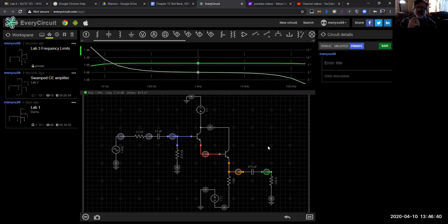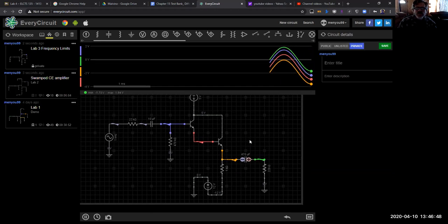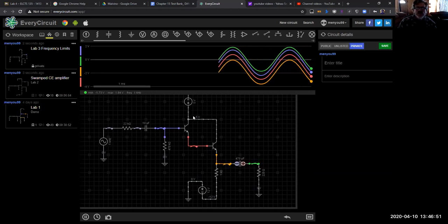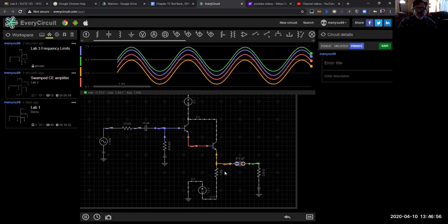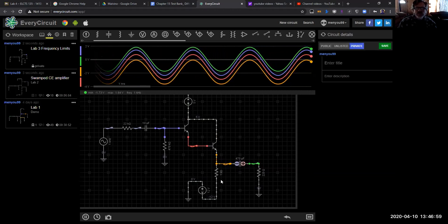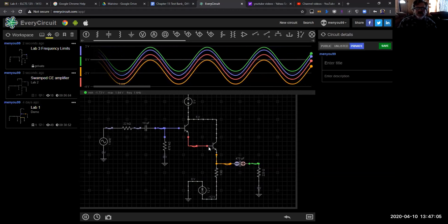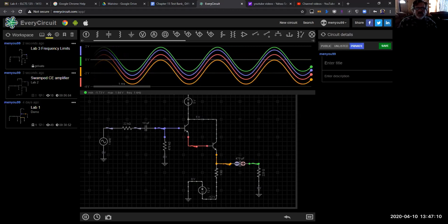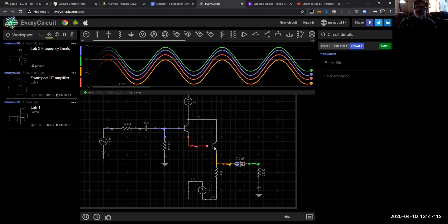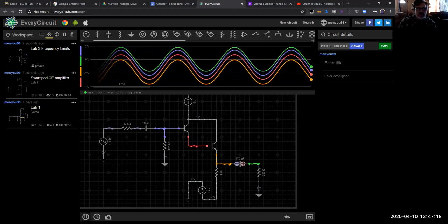As far as being affected by negative feedback, you can still see it's occurring, right? As we watch how the current flows through here, starting and stopping on the alternations, as it fluctuates we do know that there is negative feedback occurring in this case, but the way it handles that, look at that, the stability factor is much greater as we add that in there. So one transistor cascaded into the other adds a large degree of stability to the overall amplifier.